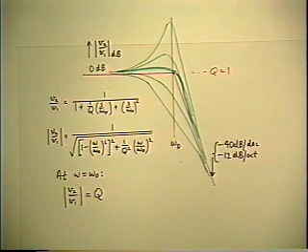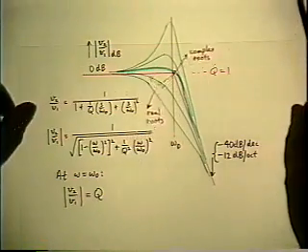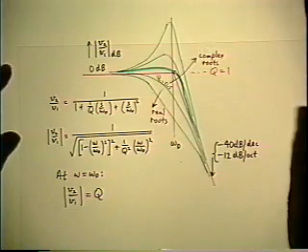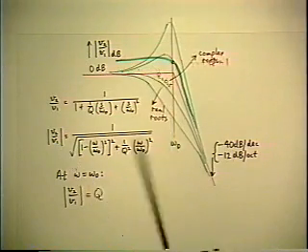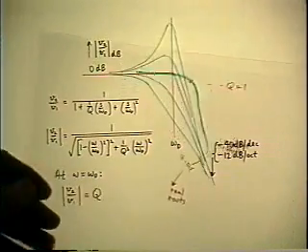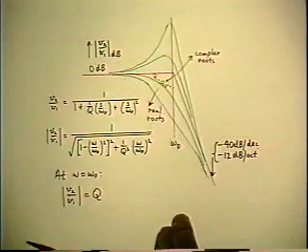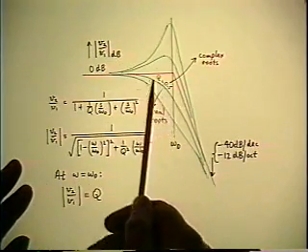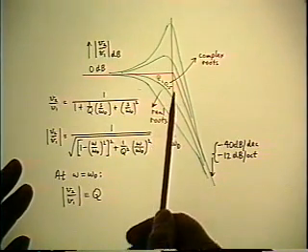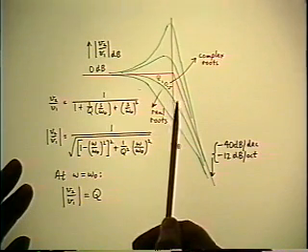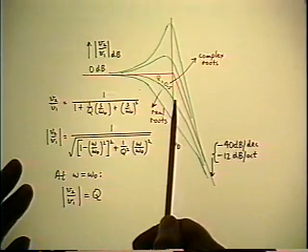That's a little different from the other way to divide the two cases, which is a Q of 0.5, which separates real from complex roots. So a Q of 0.5, of course, is less than the 1. So this curve I've drawn next below it might be a Q of 0.5, which means it would go through the point minus 6 dB at the corner frequency.